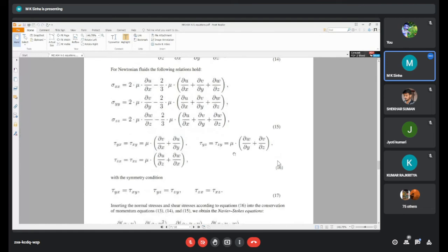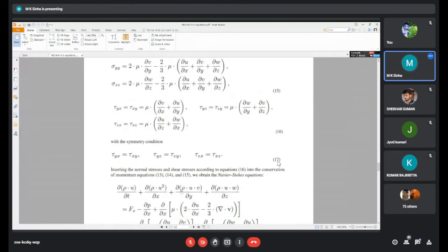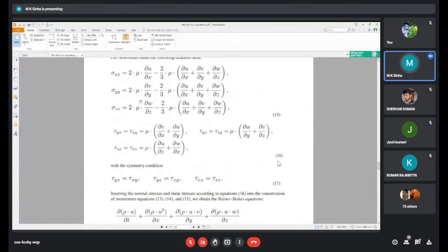So plus del/del x of sigma xx. What is sigma xx? Sigma xx is nothing but 2 mu del u/del x minus 2/3 mu times (del u/del x plus del v/del y plus del w/del z).